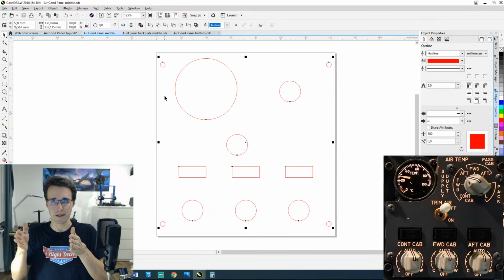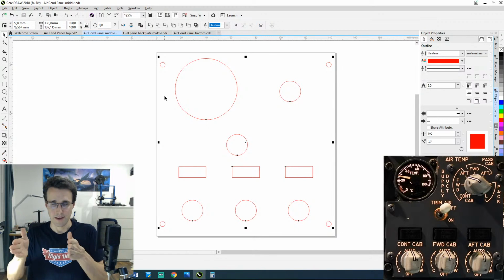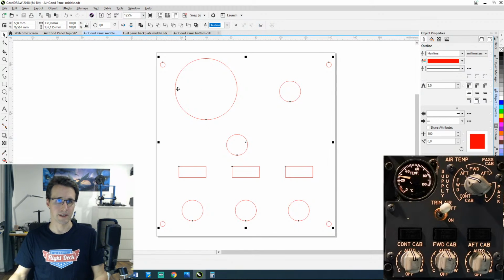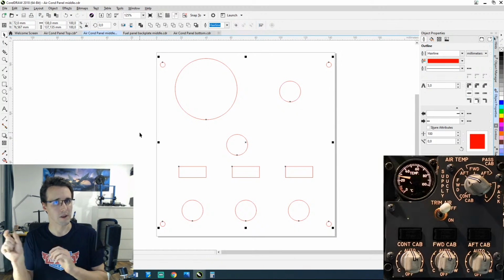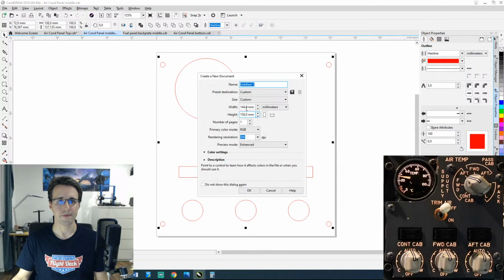The backlighting panel will sit on 50mm hex standoffs between these two overhead frame parts. So it has to be smaller than this panel here. And I have said I want to make it 12mm smaller on each side, so 24mm in whole. So this means the height will stay the same. This has worked out good.